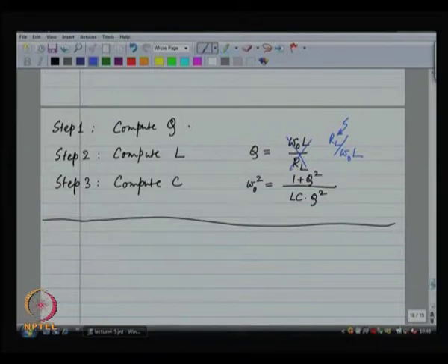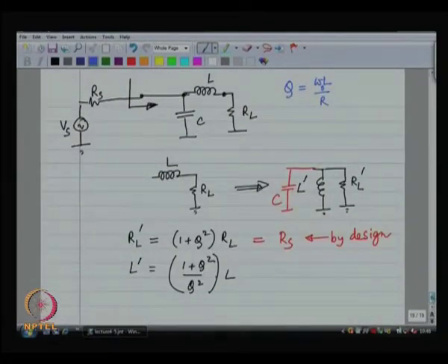resistance increases. When you have inductance in series with a resistor, when you decrease the resistance, when you make the resistance a short circuit, you get infinitely large Q, which means that you need the resistor in the denominator. Okay, that is how you keep in your mind what the correct formula for Q should be, what the correct result should be. Okay. So, Q is going to be omega naught L by R.